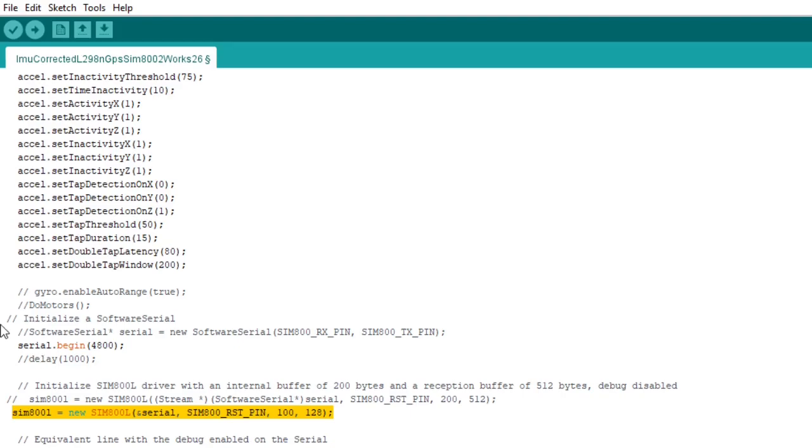So in terms of time, what causes a big delay is essentially the fact that we're running at 4800 baud rate. This does work at 9600 as well, but I've just found it more reliable at a baud rate of 4800. You can also obviously go for 2400, but then I found it's just too slow. It just takes ages. So that's a SIM800.